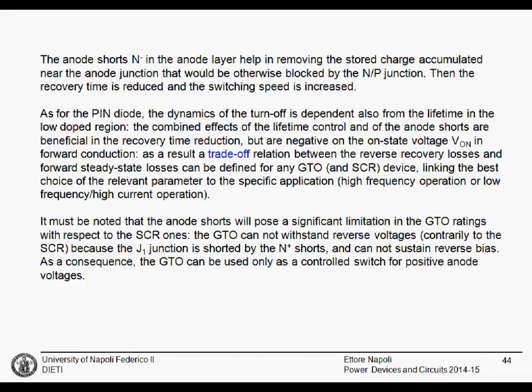The dynamics of these devices also depends, like for the PIN diodes, on the lifetime in the low doped region. If you use some kind of lifetime control techniques to reduce the lifetime in the drift region, this will obviously reduce the switch-off time and the reverse recovery time, but the on-state voltage drop will be larger.